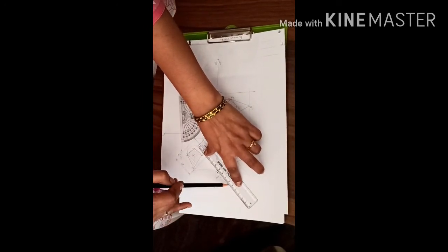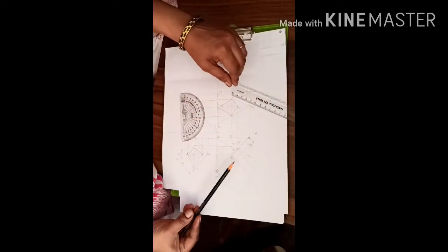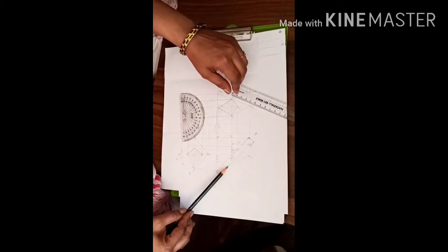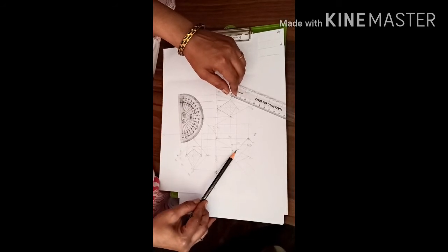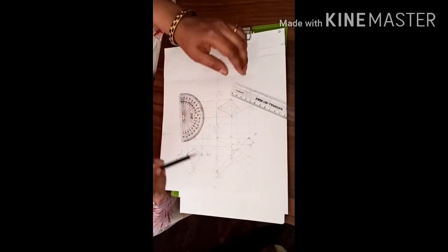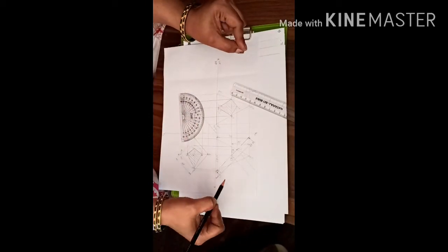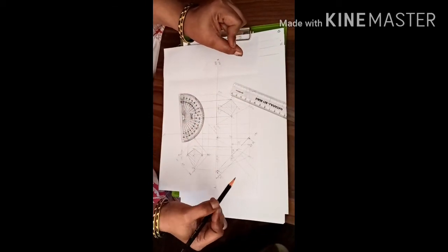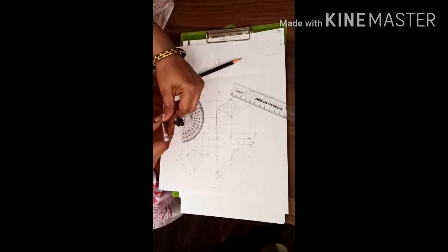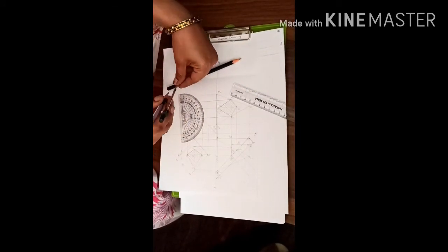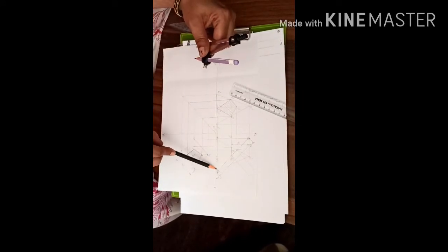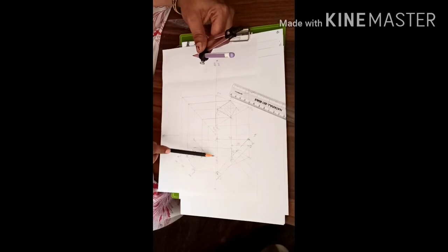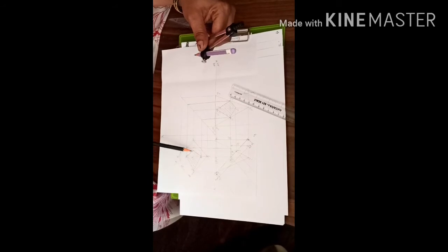One thing we have to remember here is that the x2 y2 line will be parallel to the section plane, and these projection lines will be drawn perpendicular from the corresponding points. This is very important. Now in order to find the true shape of section, with the help of compass we need to measure the corresponding distances of the points 1 dash, 2 dash, 3 dash and 4 dash from the xy line to those points in the sectional top view.